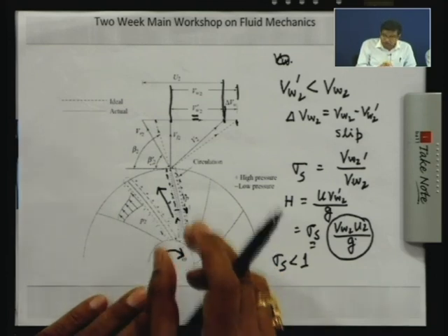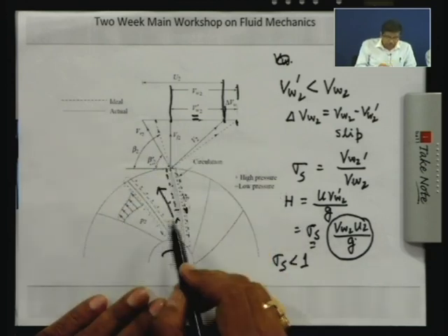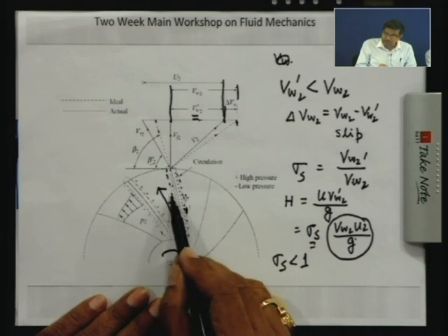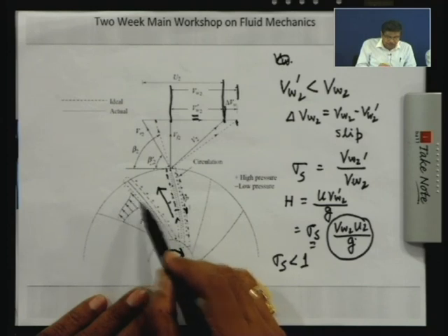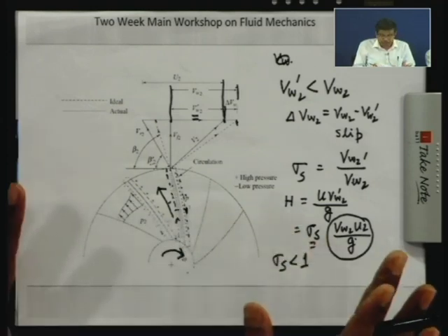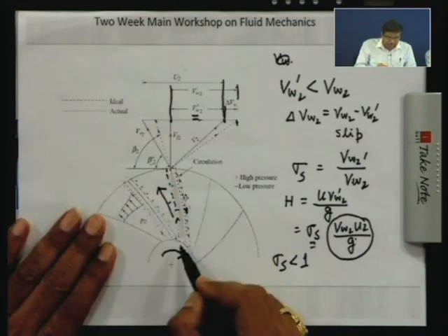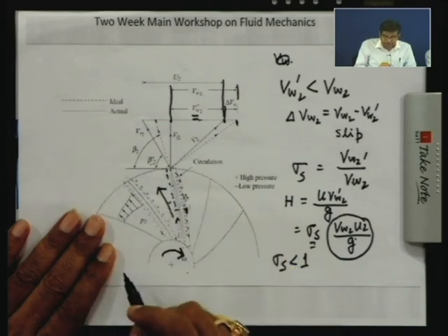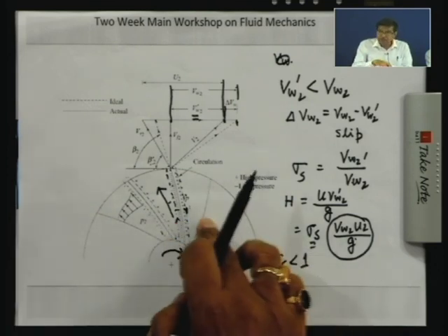So, this is a typical fluid dynamical phenomenon similar to that of flow of fluid past an aerofoil, where there is a decrease in velocity on the leading side and an increase in velocity on the trailing side, which makes a non-uniform velocity distribution in the passage. So, this is irrespective of the fluid viscosity. Apart from that, there are viscous losses, skin friction losses and other viscous losses at the entry and exit in off-design conditions when the relative velocity does not match the vane angles, but this is added to a slip loss because of this phenomenon of slip.